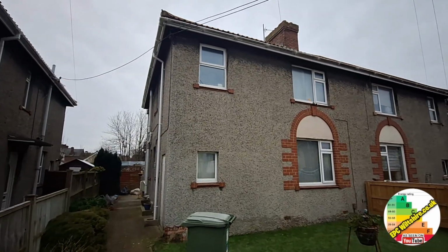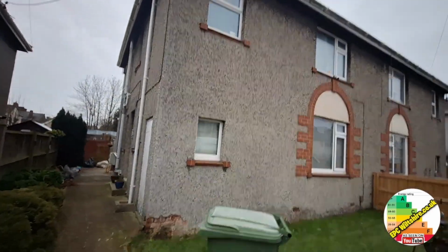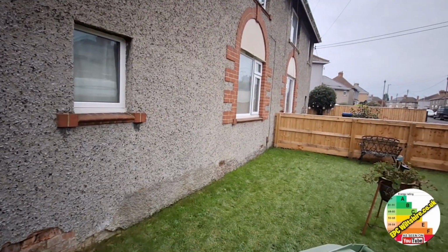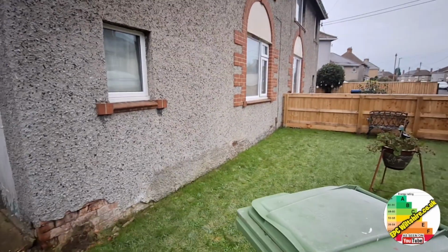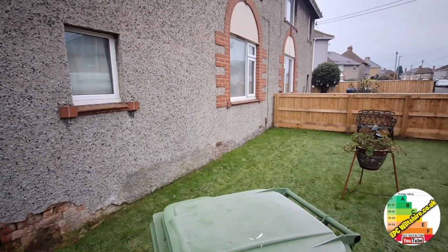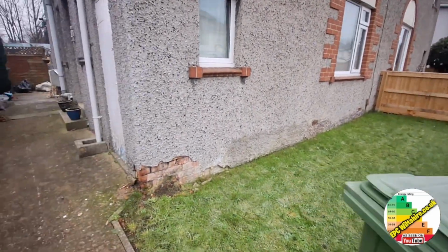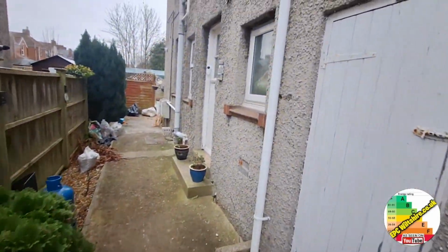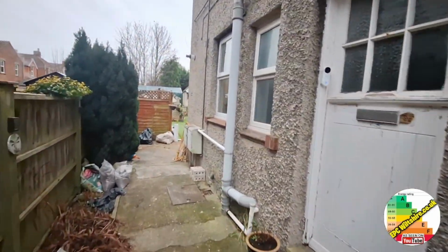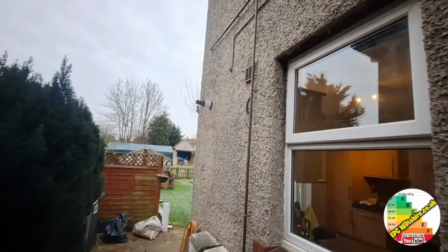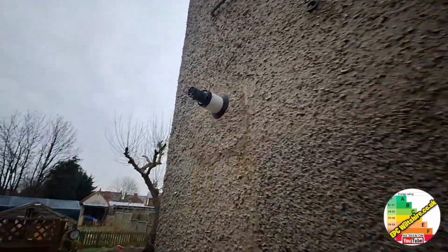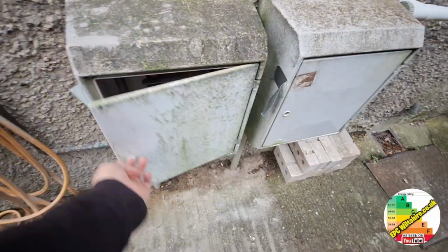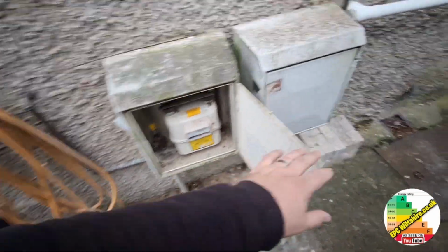So here we have a 1950s semi-detached, I believe it's a flat. We've got some ventilation points there on the floor, leading me to check that the floor is suspended timber. We've got some brick evidence behind the render, and then we have a door for the flat above, and a gas meter, and then there's a flue. So we're looking at a condensing boiler, balanced flue, fan flue. And there we have a gas meter.